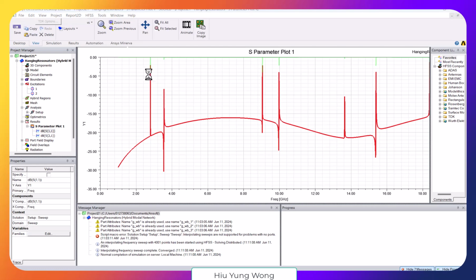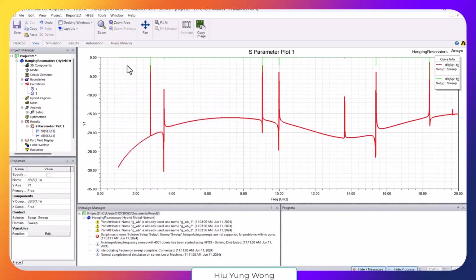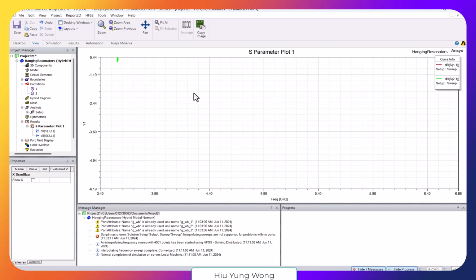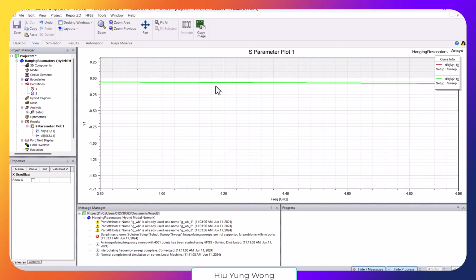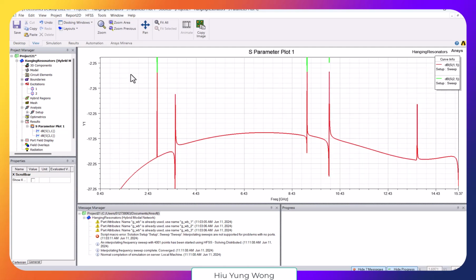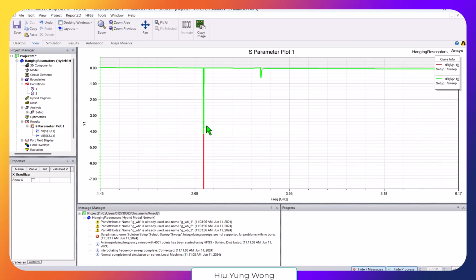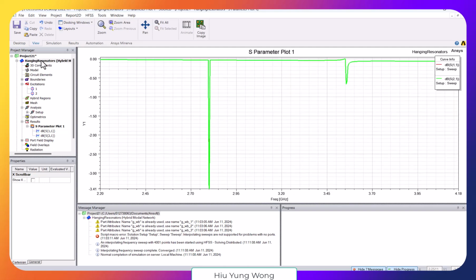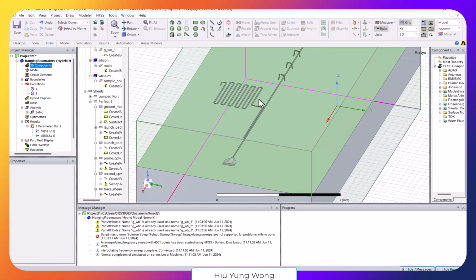So they should have about 0 dB of transmission, right? Which is 100%. It's not exactly 0 dB. We did not design it perfectly, right? But it's pretty close to 0 dB. Okay. Another thing is that we see it has a dip. Why does it have a dip? This is because when it reached the resonance frequency of this hanger, of this resonator, right? This is shorted. Then it interrupts it. It just makes the effective impedance no longer 50 ohm, so they cannot transmit through, right?